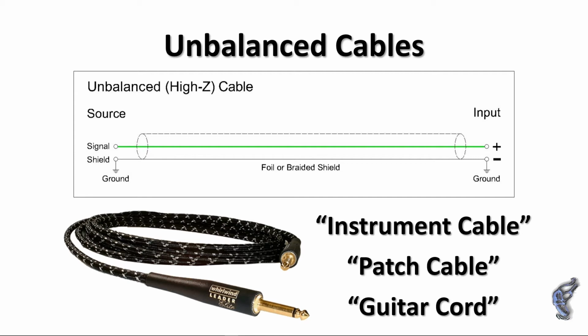It has a single copper conductor wrapped by a copper shield with a 1/4 inch phone plug connector on each end. We call this an unbalanced cable. Such cables are fine to use in this instance, although they are of limited use because longer cable lengths can degrade the frequency response and the quality of sound.